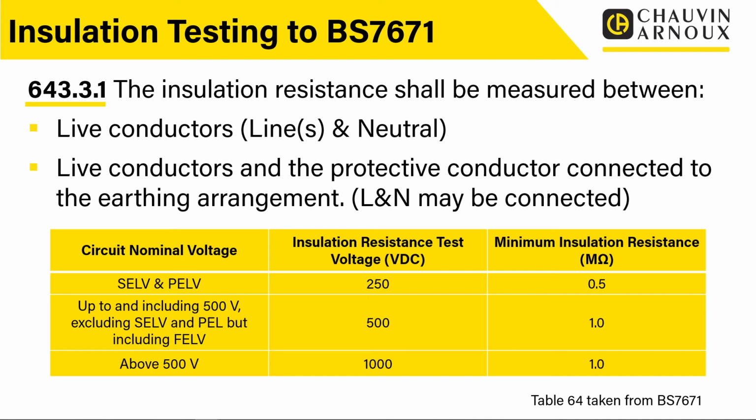Now there's very little within the electrical wiring regs that would have a voltage above 500 volts. Some circuits relating to neon lighting may fall into this category. Some considerations of PV systems potentially could get into this sort of voltage range, and they are considered separately. There's different guidance a little bit on there, and we may talk about that a little bit in the next webinar about the testing of PV systems.